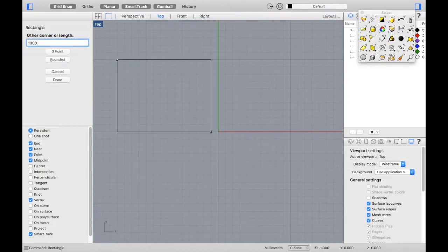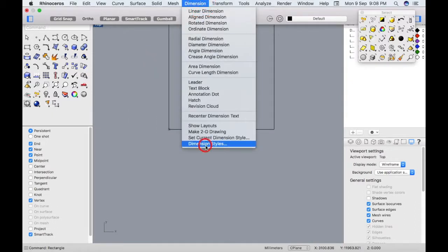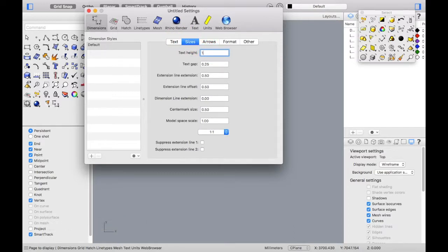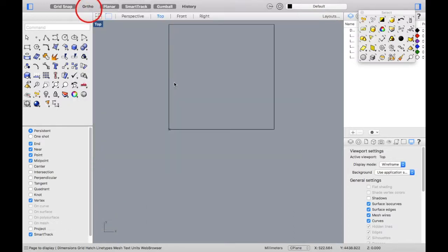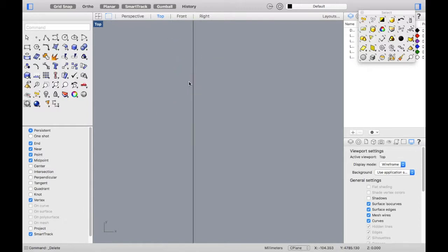Hi guys, so today we are going to be working on Rhino by creating a free-form structure made up of individual units which combines to form the entire structure. Let's begin by giving the form by creating the base, using rectangle to create a rectangle or circle to create a circle or any shape that you require.